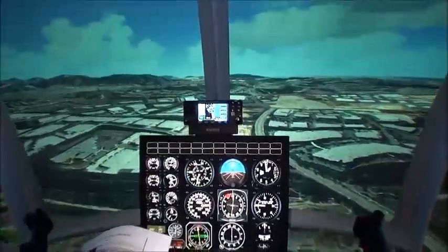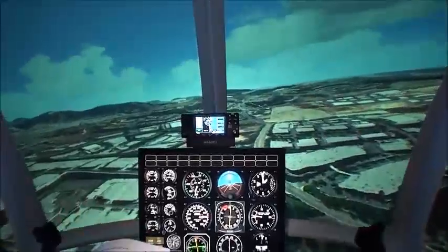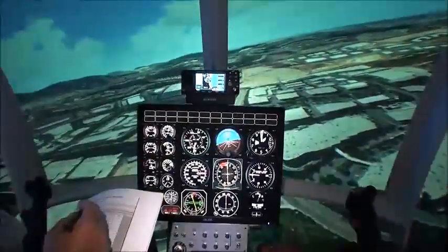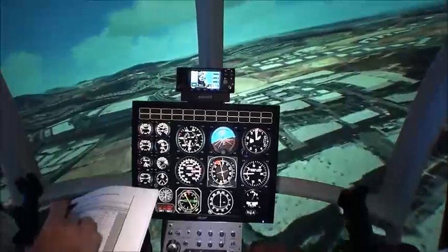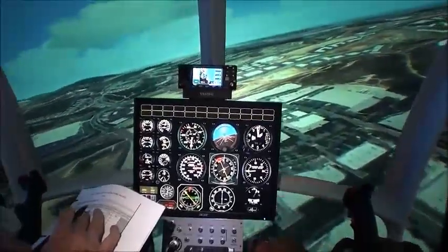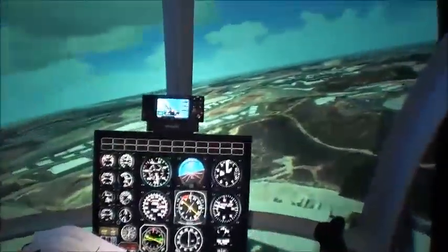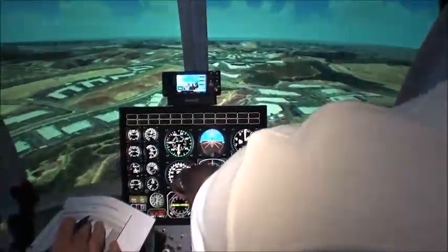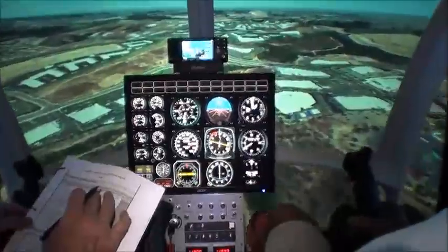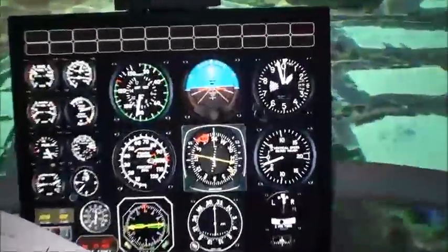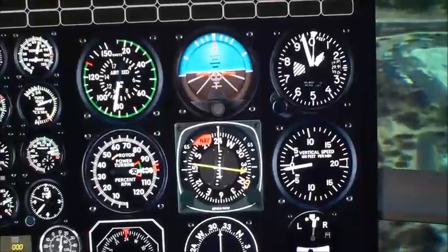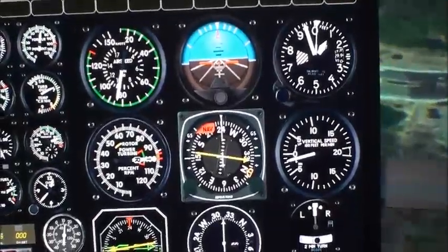And while we're on our way back to the airport, what's the procedure you're going to be doing, just so that we can show it? Okay, so I'll fly in at 1,000 feet MSL and about 70 knots. I'll count down 3, 2, 1, and I will roll the throttle down, and I will put the collective down, and I will use the collective to control my rotor RPM. I'm going to hold my airspeed at 70 knots. And then when I get a little closer to the ground, I'll start my flare and hopefully do a soft touchdown.